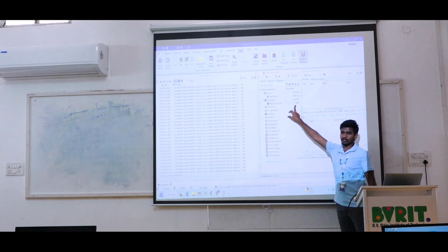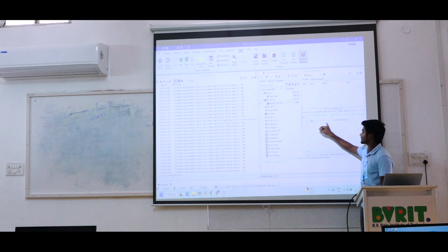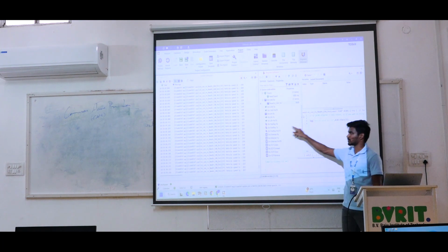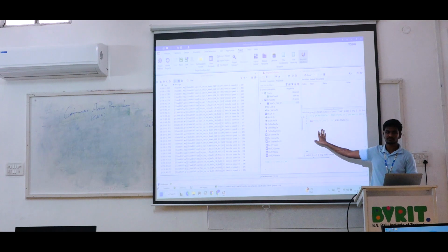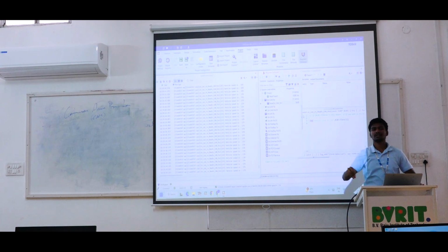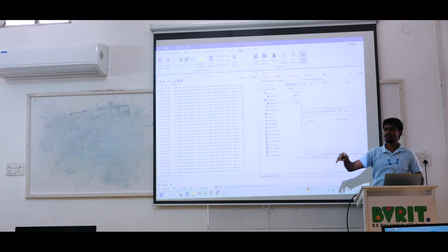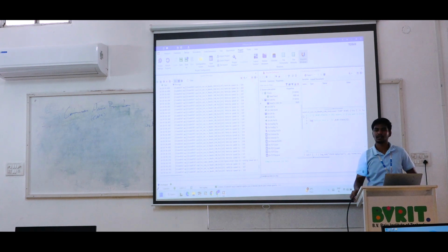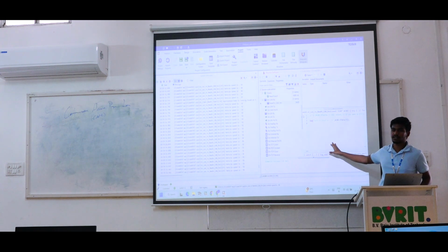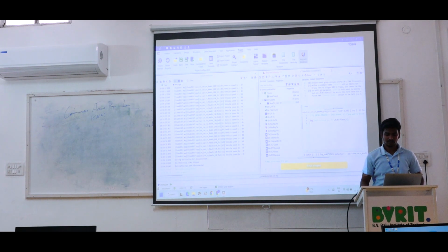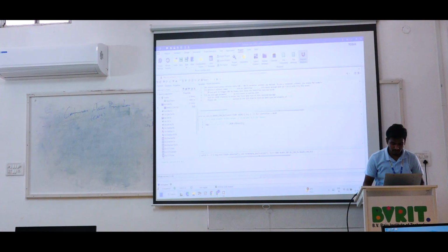Now the scripting we write is this: whenever you receive the ID number of 20, please access the byte value of 1. Whatever value is showing, please display it to me. So that is the line we mentioned. Okay, so you can take it a little bit technically. If the vehicle speed is greater than 100 and less than 150, please indicate it to me. Like that we need to mention. So you just stop the scripting here. Just to stop the scripting, please maximize your window.